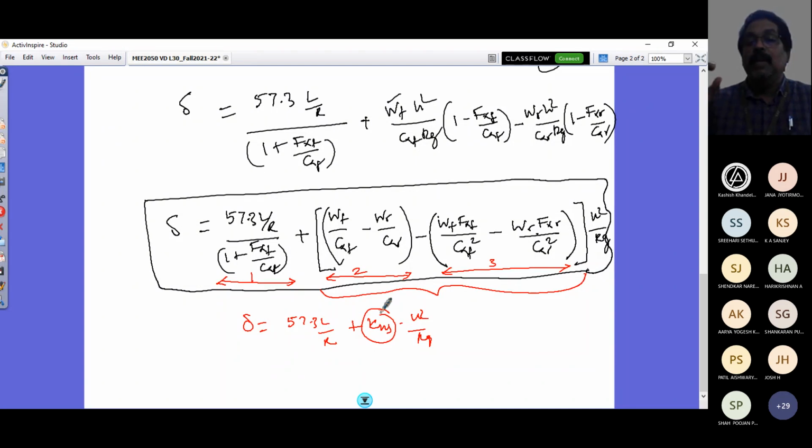What is to be remembered here? You may wonder what happened to the camber change effect and the lateral load transfer effect. We are not taking all of them. If we account for all of them and try to work it out, we would have a very long equation and it becomes a cumbersome process. That is why we state the assumptions and the model description clearly, and then we go in for deriving the requirement.